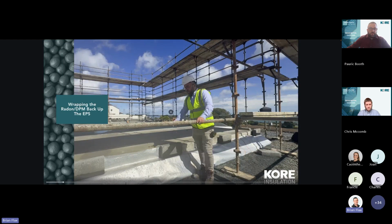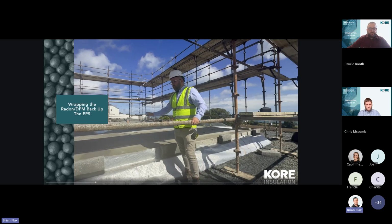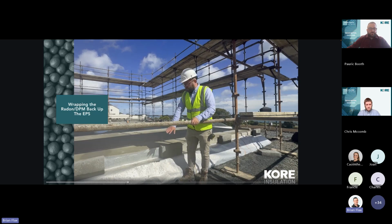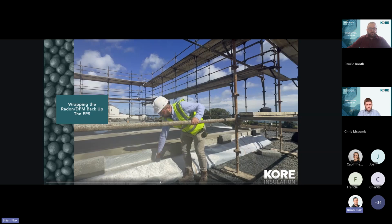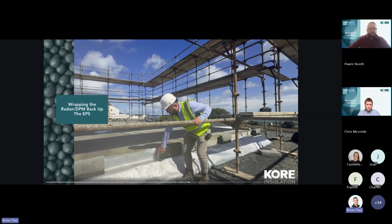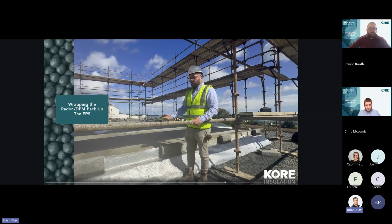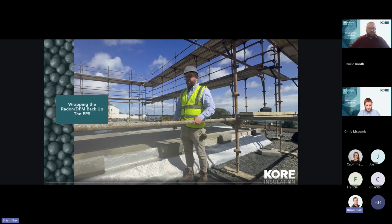So here we have an F-profile foundation. This foundation suits a timber frame house with external blockwork masonry on the outside. You'll see that the temporary shutter has been removed and the outer ring beam concrete has been poured. The radon barrier has been wrapped up the external ring beam, back up the upstand, and left to sit inside. The timber frame will then come with its DPC below its sole plate, which overlaps that, and the EPS has been protected from any contaminants or solvents coming through it, but also there's a DPM there to prevent any moisture coming inside.